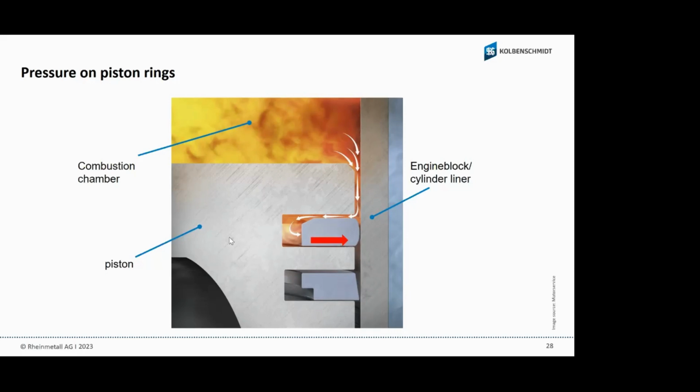And this is completely the easiest way that you can explain to the customer. And this is why it's so important in which condition they use it. And maybe when you can read the ECU, in which condition they drove it, then it's very easy. MAN, Deutz, first they look in the ECU and say, okay, you're using this engine in this load condition. Sorry, we cannot accept any oil consumption.